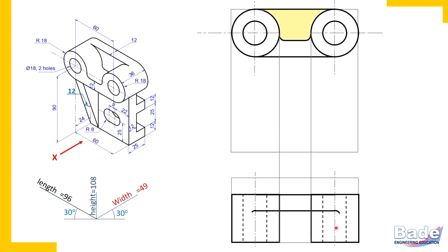And watch these small curves here. These small curves are a diagrammatic representation that indicates a tangential joint between two surfaces. So when a flat surface meets a curved surface tangentially, then in orthographic views, this is how we denote that tangential joint. And that sharp edge, which I erased here just now, is replaced by this curve, indicating it is not a sharp edge here, but a tangential joint. So this is how we have corrected the joints here. Now one more thing. These two edges are also to be erased.